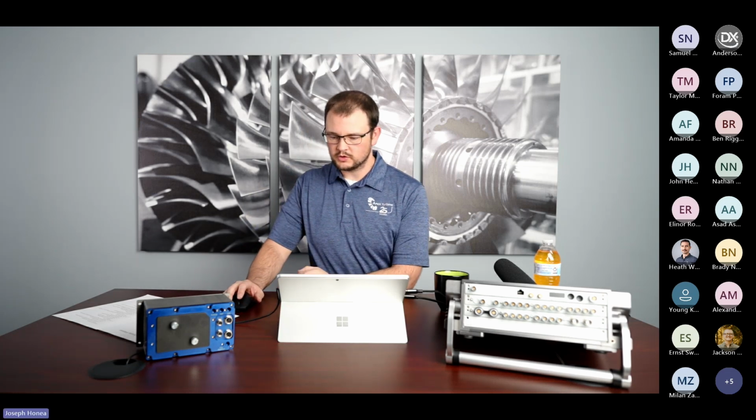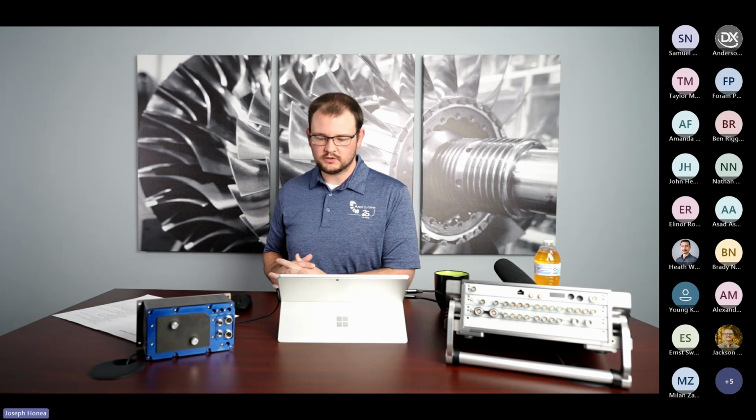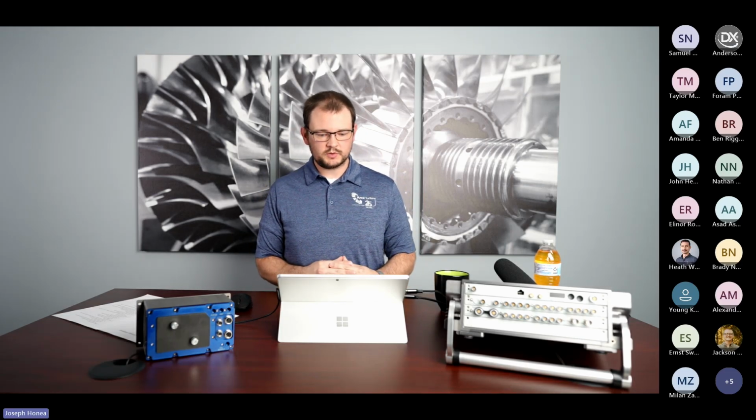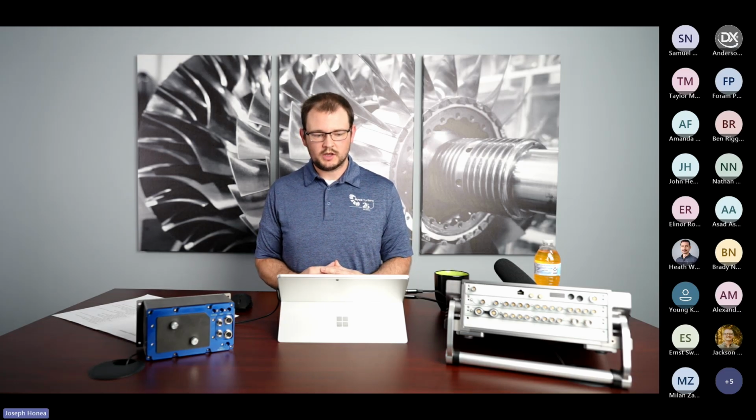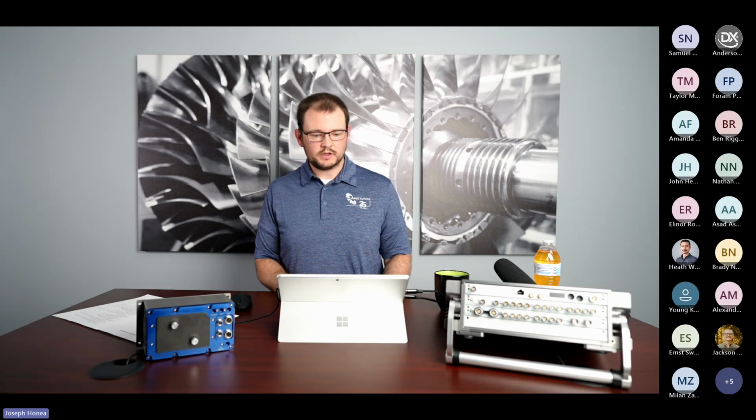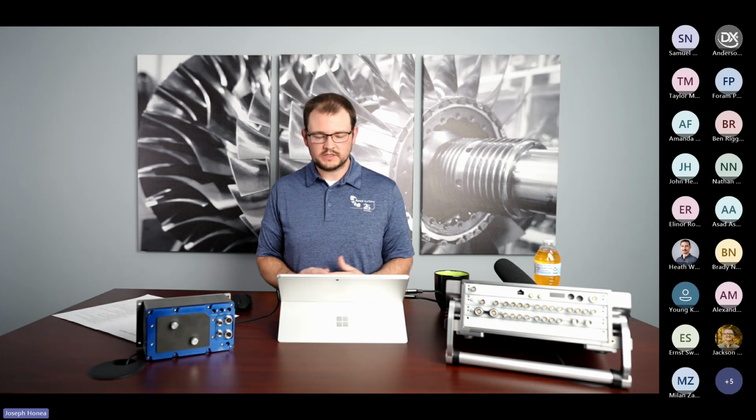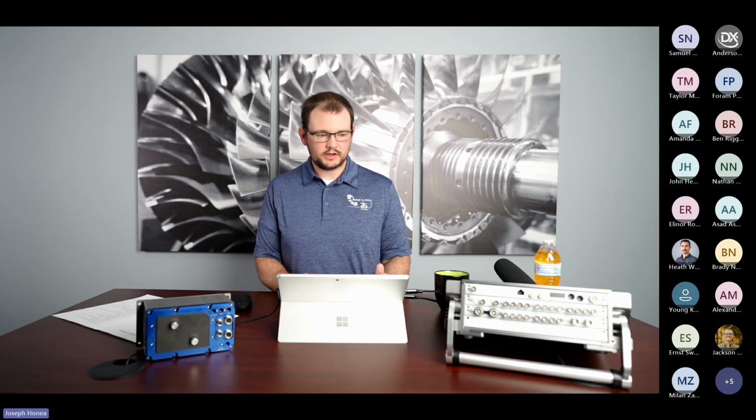Okay, going over DX Plus and handling of time synchronization. So time synchronization of DX Plus occurs using the absolute timestamp that is provided from the device. The majority of the hardware platforms that are coming out now support PTP that ultimately provides up to or around a 300 nanosecond accuracy value.